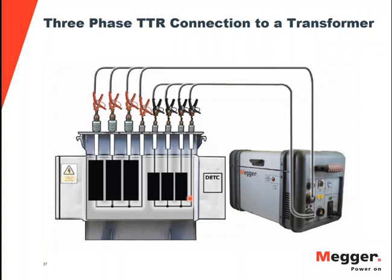If you want to be more proactive, you can connect primary and delta tertiary in series and do dual injection to speed up the process of core saturation. But those are the things that I would keep an eye on. Make sure that you give enough time for delta winding saturation, because delta windings on the secondary side are kind of tricky. So, yeah. Thank you, Dinesh.